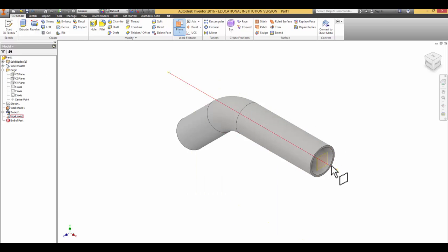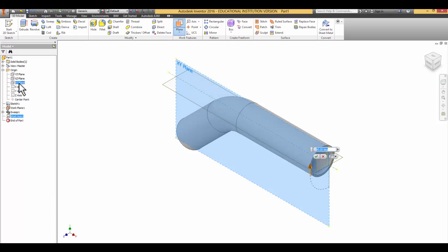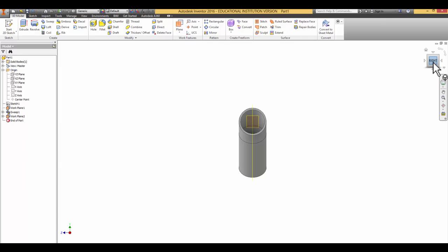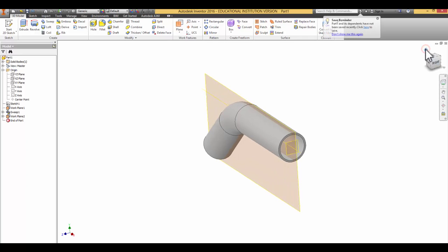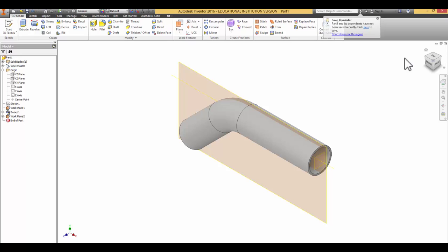And what I'm going to do is I'm going to say I want it to go through this axis, and I need to figure out which plane it is. I want it to be the one that is vertical through it right there. And so I'm going to click, and I'll be honest, I don't know why they have it default to make it turn 90 degrees. If I pick that plane, I want it to be that plane. So you tell it 0 degrees. And if you look at it, you can see that plane is going through the center of your part. It is bisecting your part.